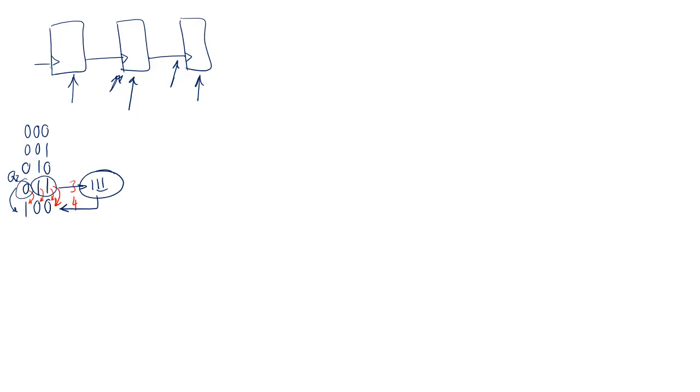And then, well, in reality, you haven't actually reached the 1 1 1, but your next block is going to think that you have reached it. Because of these kinds of problems, we really want a counter that is fully synchronized.